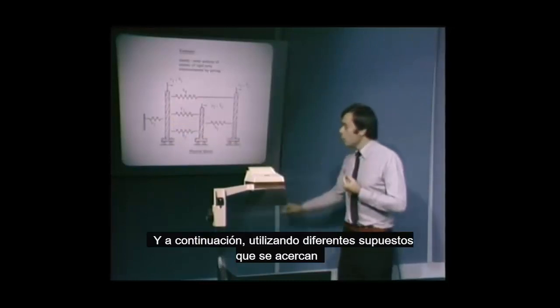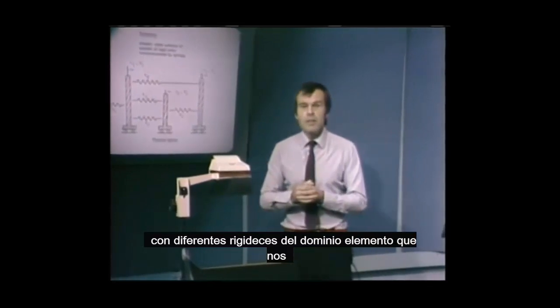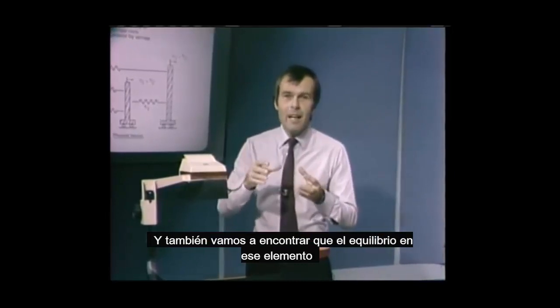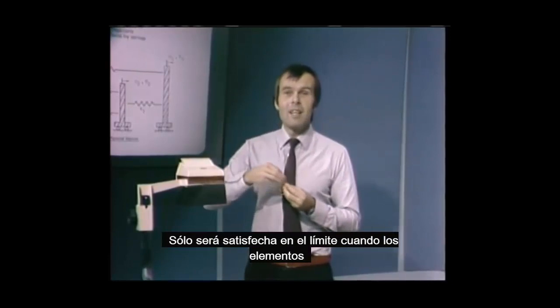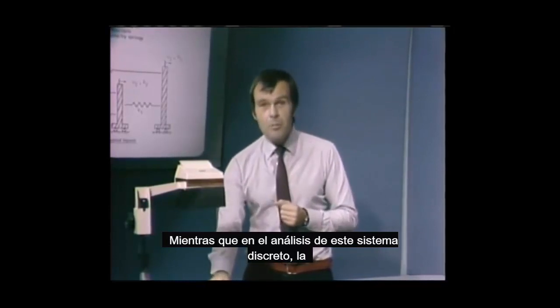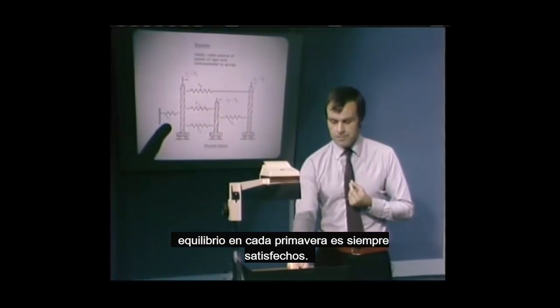And then using different assumptions, we are coming up with different stiffnesses of the element domain that we will be talking about. And we will also find that the equilibrium in that element domain is not satisfied. It will only be satisfied in the limit as the elements become smaller and smaller, whereas in the analysis of this discrete system, the equilibrium in each spring is always satisfied.